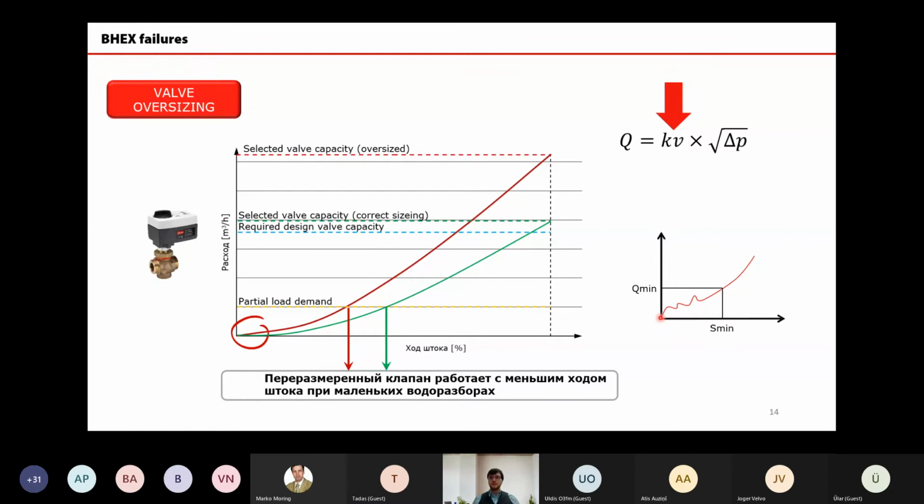So if I have a control valve working in oscillation mode, meaning it closes, opens, closes, opens, for the heat exchanger it creates oscillation of temperature. So the heat exchanger gets very, very hot, up to 110 degrees, and that leads, of course, to overheating of the secondary side. Controls immediately send a signal for the primary valve to stop this flow rate, to limit it, to close it. So the flow rate is closed on the primary side of the heat exchanger from 100, but the tapping on the secondary side is still continuing.